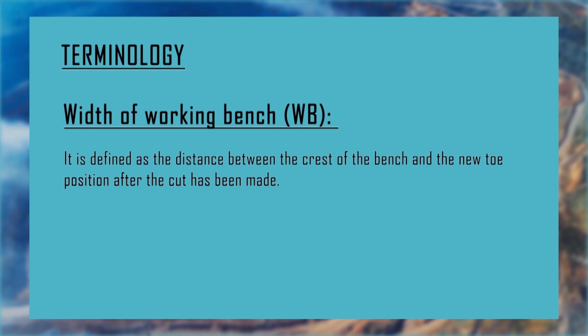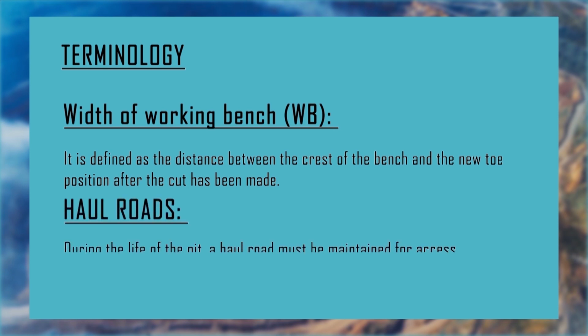It is dependent on the width of machinery, whether the bench may be single lane or double lane. Haul road is the travelling road in an open cast mine. First of all, it is developed because the whole transportation operation is carried out through this road, and this road should be maintained throughout the life of the pit. It is continuously maintained, as the whole transportation system depends upon this.